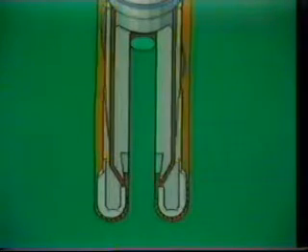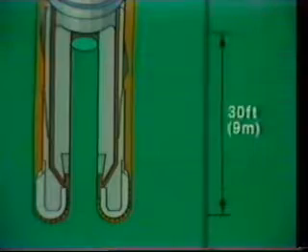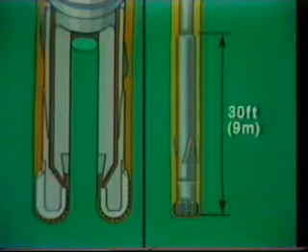and outer barrel, approximately 30 feet or 9 meters in length. The barrels may be joined in multiple lengths for increased length of core recovery. In the J field, for example, it was common to run 3 lengths at a time. The bit is attached to the outer barrel. Conventional core barrels are typically 3 to 5 1/4 inches or 7.5 to 13 centimeters in diameter.